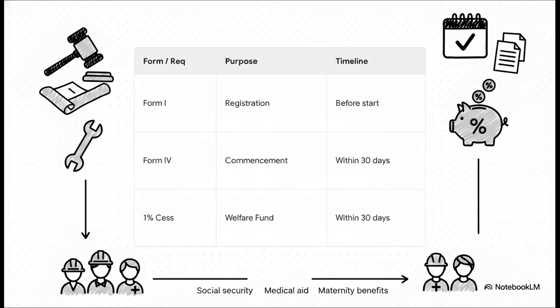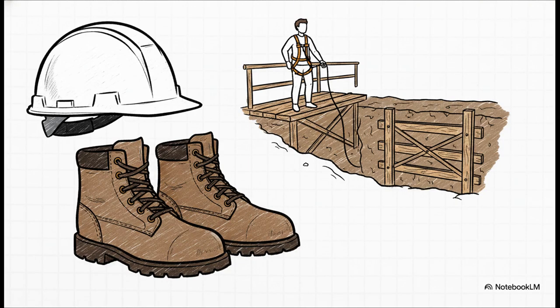your project. And because real human lives are literally on the line out there, enforcing these Indian standard safety protocols is 100% non-negotiable. We're talking helmets matching IS 2925 and safety shoes matching IS 15298. If a worker steps above 1.8 meters, fall protection is legally required. If a trench dips below 1.2 meters, you must shore or brace it to prevent a cave-in. At the end of the day, their safety is your ultimate responsibility.